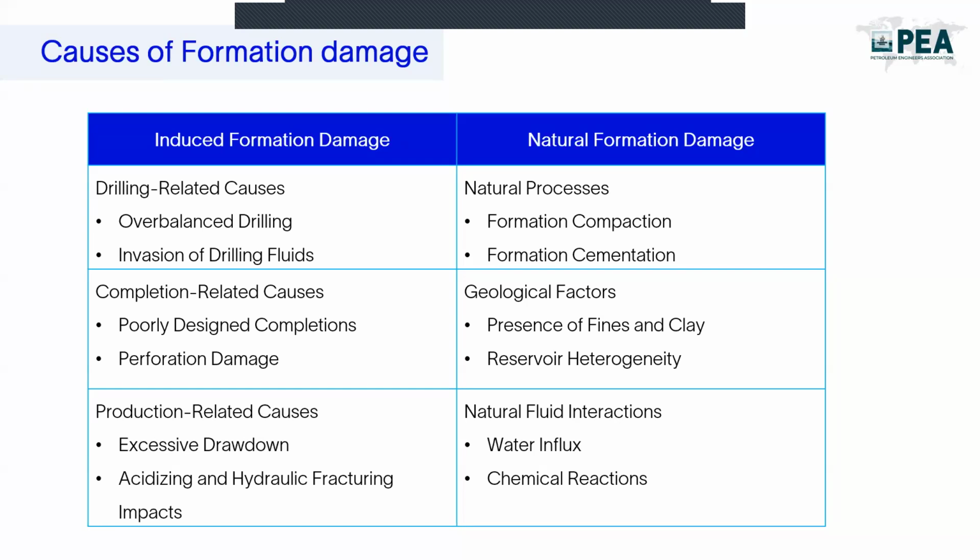As you probably know, sometimes not perforating the whole reservoir, the whole oil zone, may lead to what we call spherical flow, which could be detected while analyzing the pressure transient analysis. And this induces another skin due to the partial penetration of the reservoir. So inadequate installation or selection of our completions may raise some sort of damage.